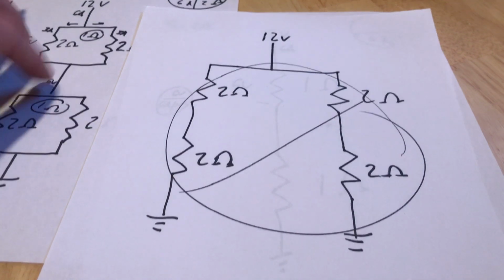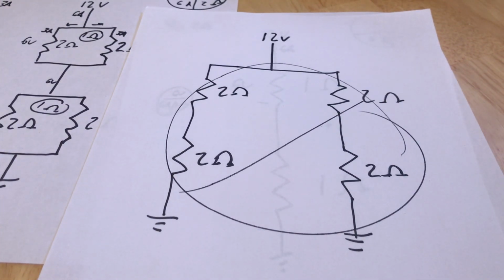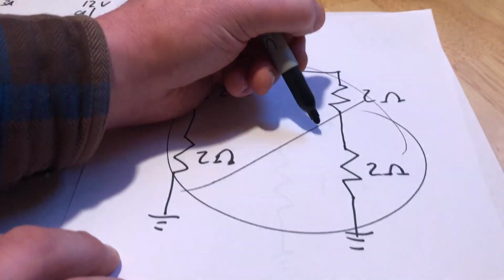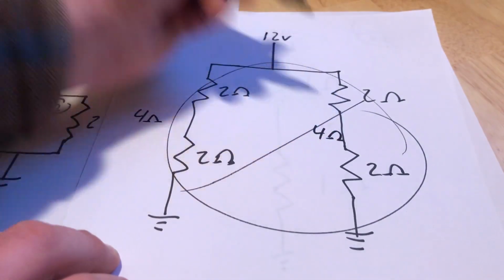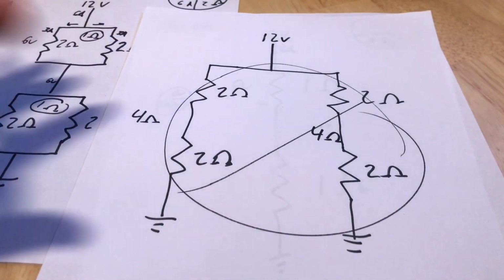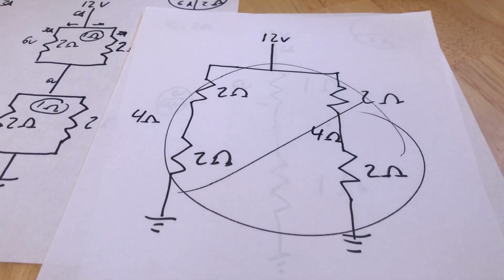That is not the same circuit that's right here, okay? This would have a leg resistance of 4 ohms and 4 ohms, okay? It's not the same. The amount of current flow that gets limited here is going to be different. The way that voltage drops as you go across it is going to be different, okay?